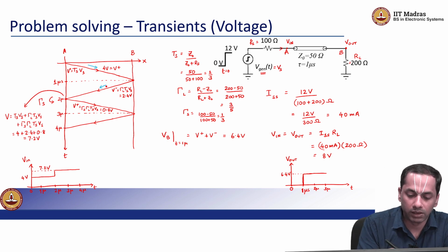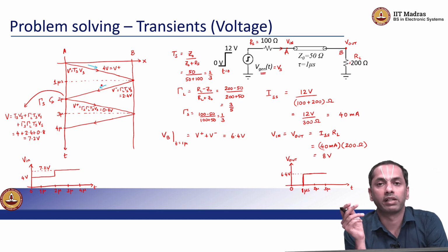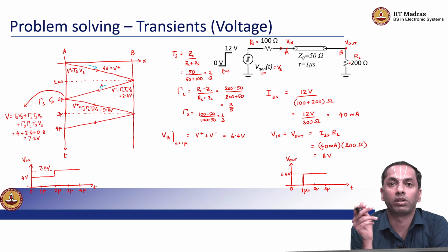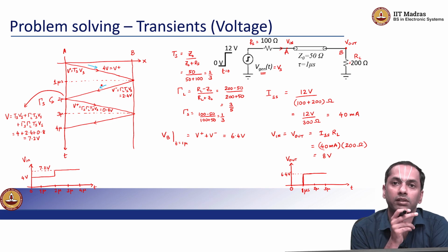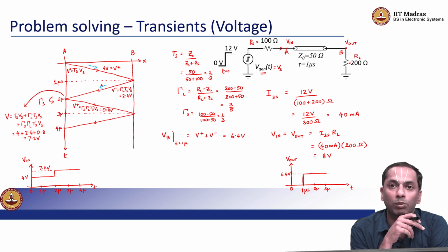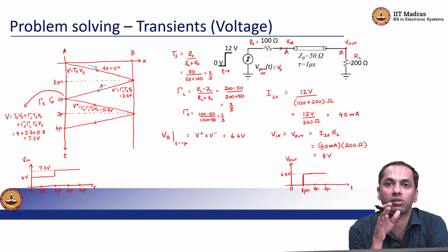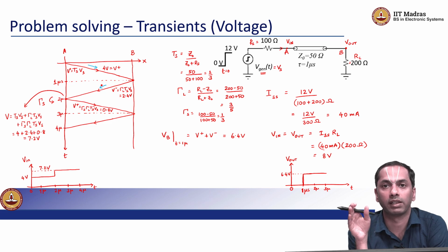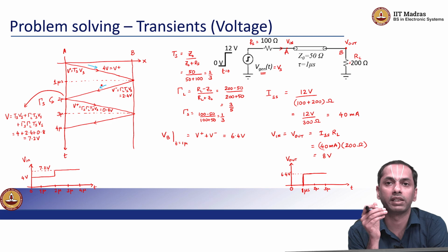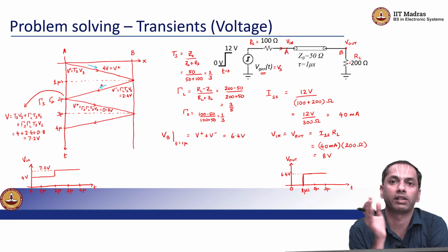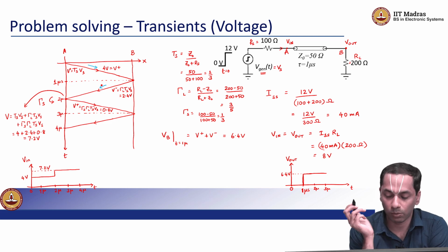So, when I am coming backward, the currents and voltages are essentially charging the line to 6.4 volts along the entire transmission line. Then again there is a reflection at the input, and the reflection is an amount 0.8 volts. Now, this 0.8 adds on to 6.4 to give us 7.2 volts and the entire line gets charged to 7.2 volts, right, and then there is a reflection again, and we are going to see that the line is going to eventually get charged up to the steady state value of 8 volts uniformly throughout the entire transmission line, right. This is what you expect.